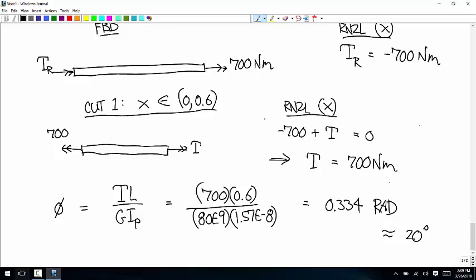So if you had something that was 5 miles long and you torque the end of it, you'd get this thing to rotate a full time around or whatever. That's a huge deformation, it seems like, macroscopically. But each individual local deformation is still really small because all of that deformation is happening over 5 miles. And so even though you have a big macroscopic deformation, you have really small strains. That means you have small stresses. And this is still totally in that linear range. We're still not talking about permanent deformations. If you let go of it, it would happily go right back. And you've seen that happen, maybe with torsion springs. It's sort of the same idea.